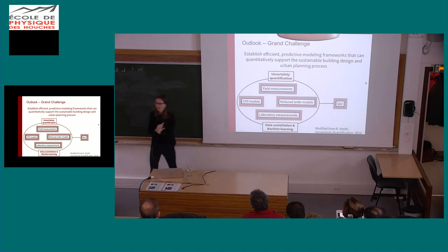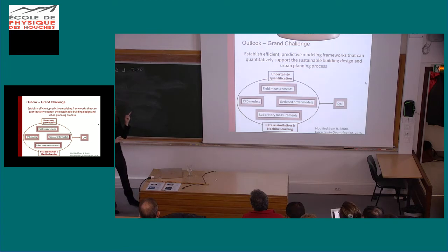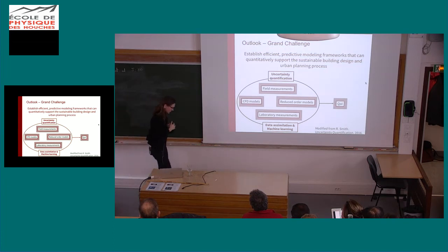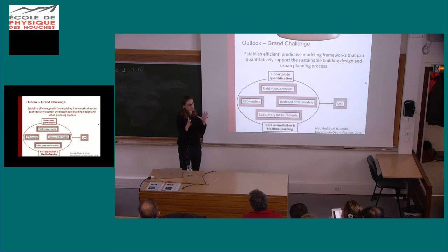For the surrogate model, we use this polynomial chaos approach that I showed you, and we use a quadrature-based method. It depends a little bit on the case. This is kind of complex. I think the first thing is what we did works really well if you have a relatively small number of uncertainties, because we use numerical quadrature techniques. And if you have a high dimensional space, you need to calculate an integral over a high dimensional space. So you have a problem there, right?